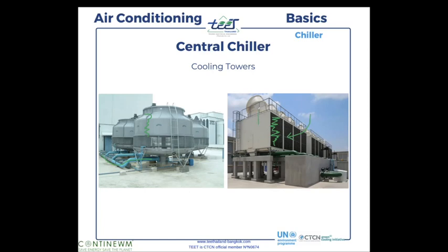And you have a big fan here that extracts the air outside. In the middle you have this kind of network where the water is sprayed in small droplets, the water that you take from the condenser of the chiller, which is hot. So you bring this hot water to the top and spray it through this network. With the fan, you suck the air from outside that passes through the water. The air from outside cools the water a few degrees, and the hot air is extracted here, okay?